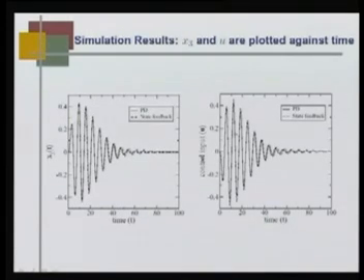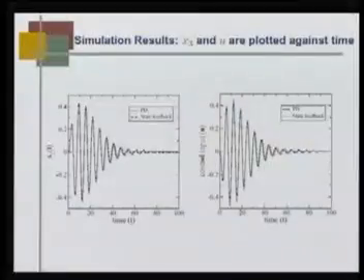That also should come to rest, because the cart was disturbed. Although the pendulum was in the initial position in the beginning, it will start oscillating, and that oscillation will gradually slow down, and in the same amount of time this has reduced to 0, for both the PD type of rule base and state feedback type of rule base.